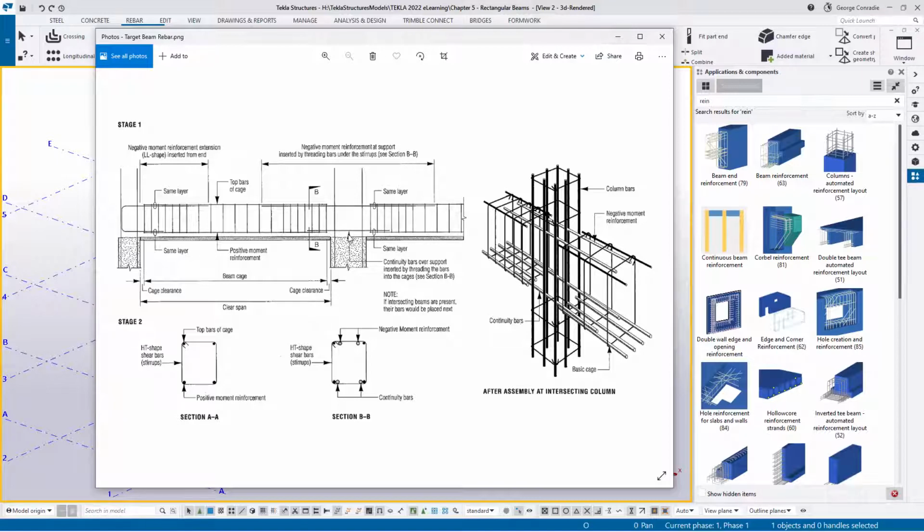There's no positive moment there. The positive moment is in the middle of the beam. So that's where the heavy lifting will be, and pretty much the same on the end, because if this column is regarded as fixity with the beam, you'll have another negative moment up in this column, and therefore the splice is a bit further out. So we'll follow this guideline very roughly in terms of the reinforcement.